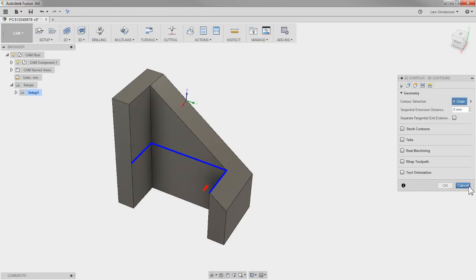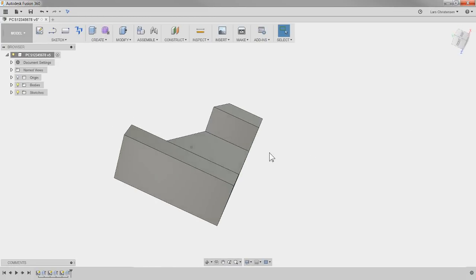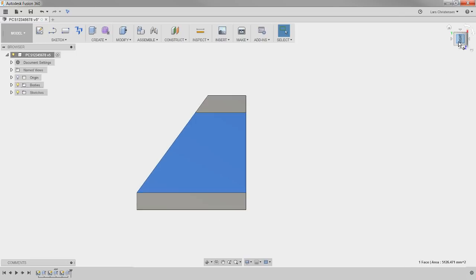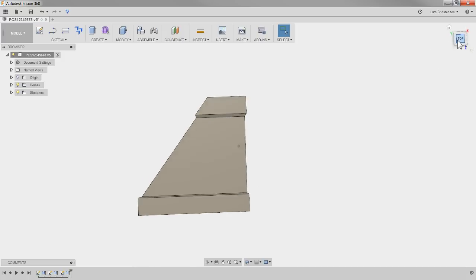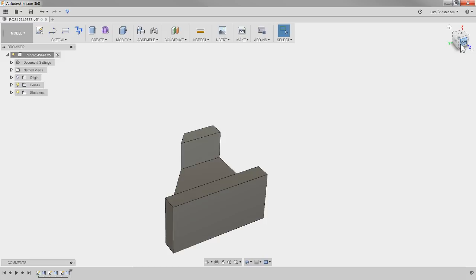That thing where you can change the view, right? Let's get out of this because I moved things around. If you think that this should be top, not right as it is here, just move it over to the right, right click, set current view as top, and you just made magic happen. You just moved that over. So now this is top.